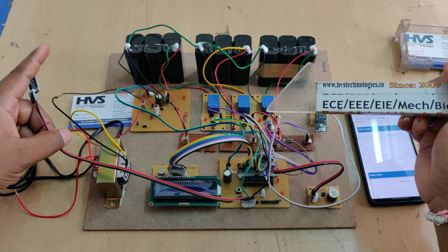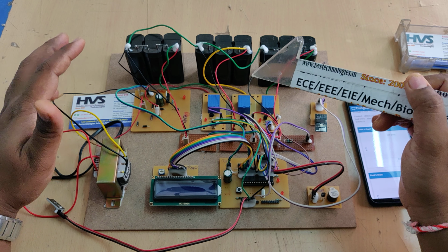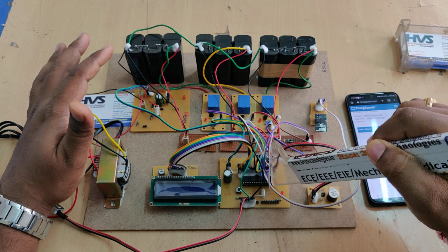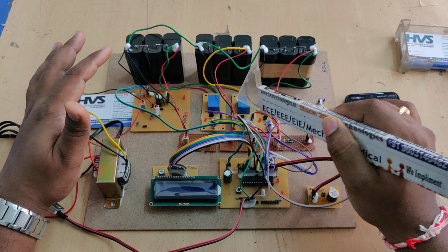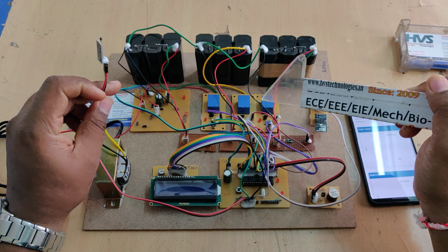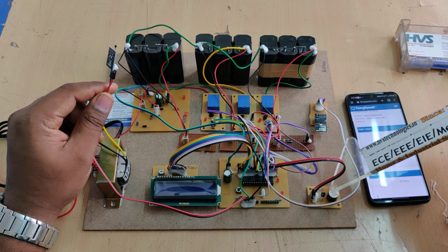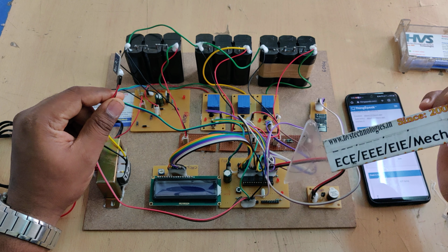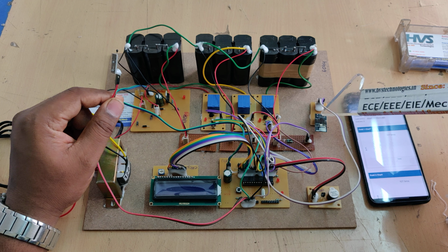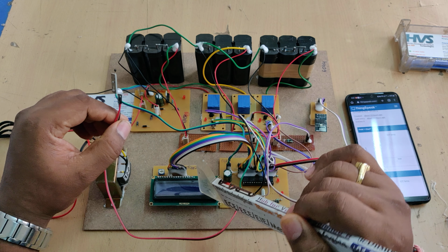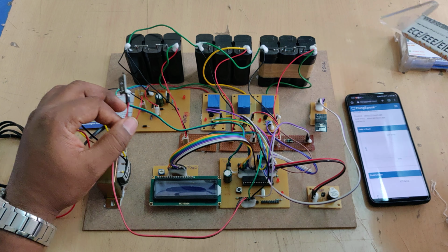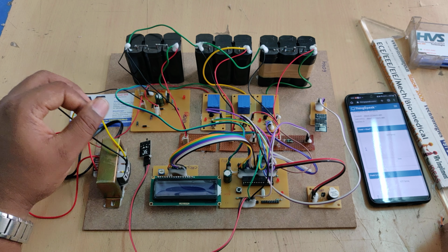Whenever the voltage level is below 10 volts, as an indication of low battery voltage for the respective battery pack, the relay will get switched on. That is done from the microcontroller at pins C5, C6, C7. Whenever the temperature crosses 43 degrees centigrade, the system provides audible alerts through this buzzer, which is connected at C4. The data is continuously uploaded to ThingSpeak with the help of this ESP8266 Wi-Fi module, connected at B0, B1, and the status is continuously monitored on the LCD screen, connected at pins B2 to B7. These are the main input and output modules in our project, along with the workflow.